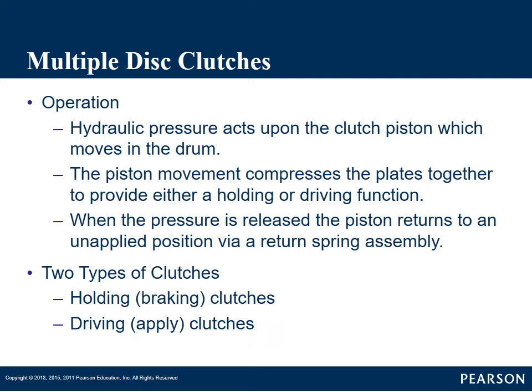we use. Then when we want to downshift, or we don't need that clutch pack applied anymore, the pressure is released from the back of the piston, and the return springs push that piston back to its rest or unapplied position.